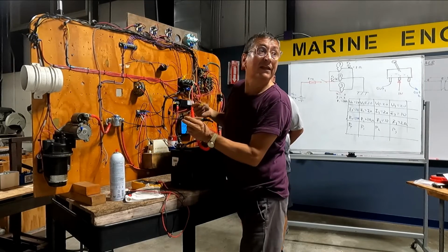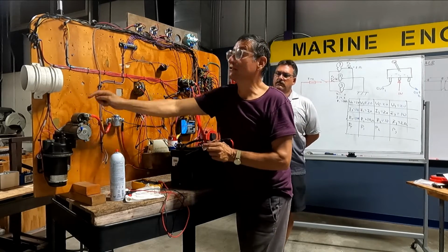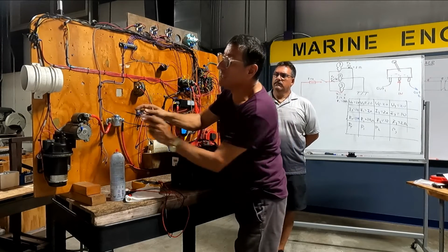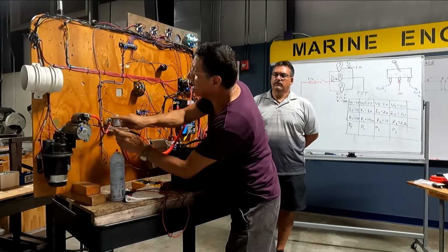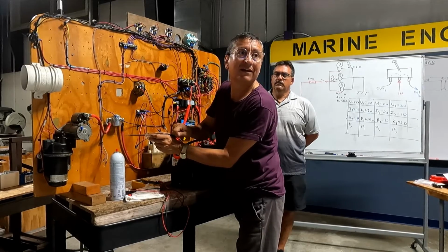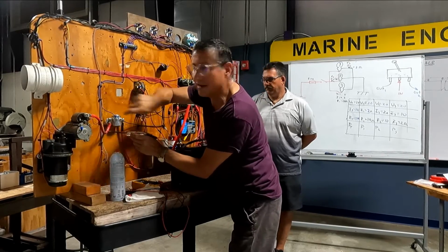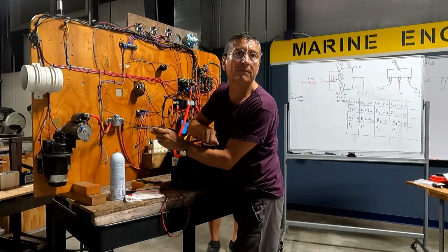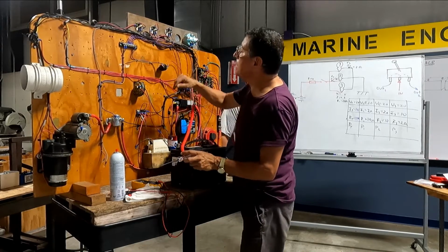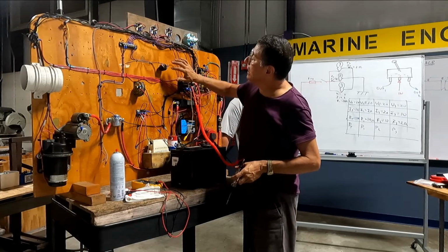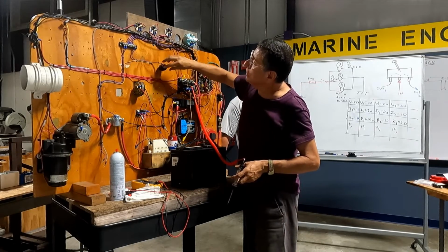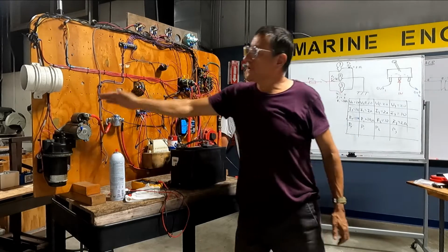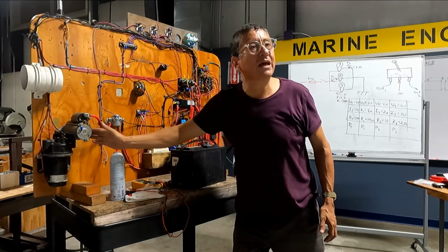The solenoid closes the gap, but the current doesn't pass because I need signal here and signal here at the same time to bring the current and push the bendix. Everybody follow me? I need signal in both of them at the same time. Okay, I need to connect this with this and this together. You discover that the start motor is good.